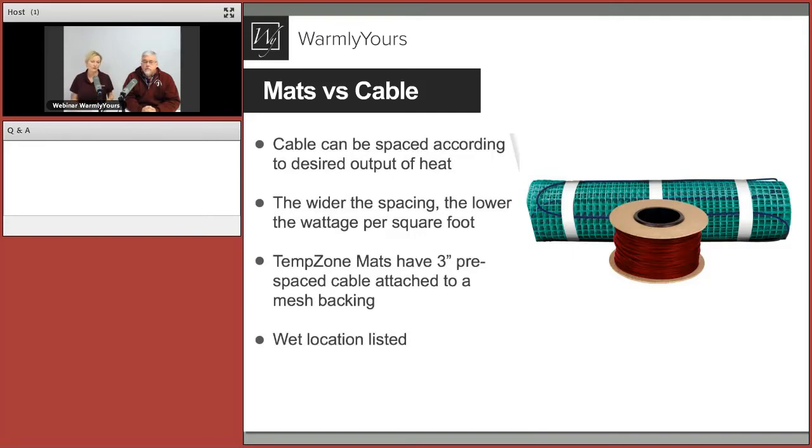I also like to share that if you're in a somewhat warmer climate, I'm originally from Baltimore, we don't know winters like you guys know here in Chicago, then you could consider spacing your cable a little further out because you don't need as much heat and as fast. But I do like to always recommend that if you're doing a master bathroom, that's a place where you're cold.